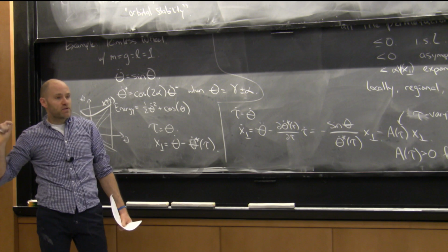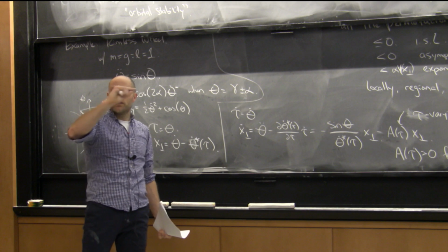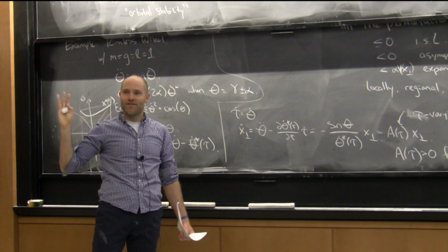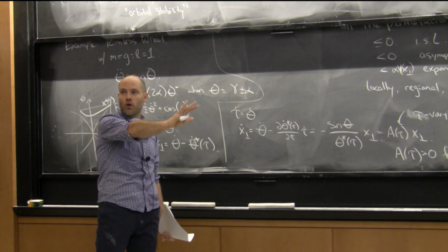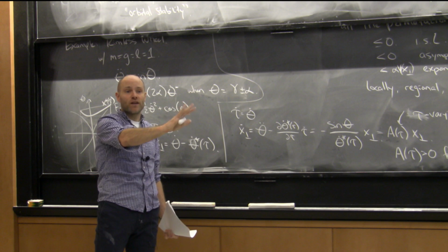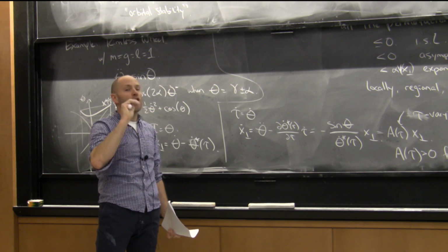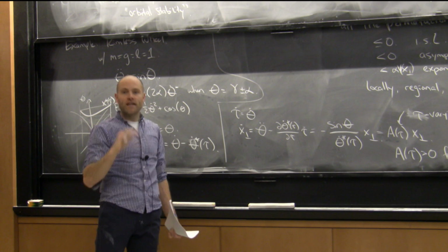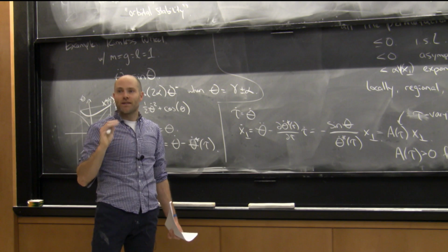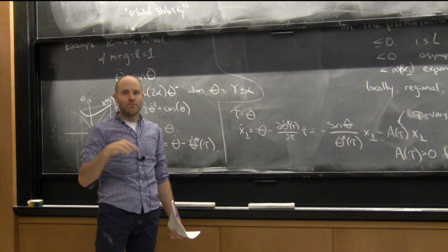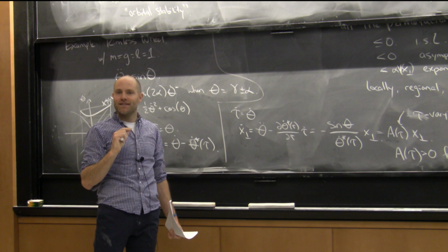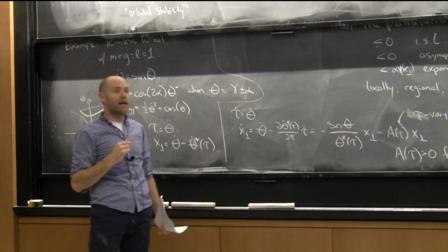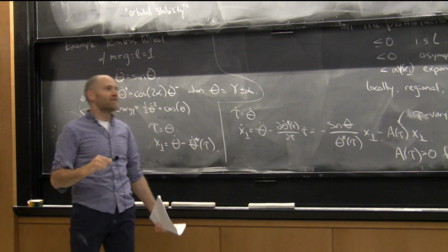You can have systems that in the short term diverge, but over time, ultimately, the integral of the total solution gives you something that performs well over time, but instantaneously, you're actually losing control authority. And that happens all the time in legged robots. So certainly, for instance, in running robots, once I leave the ground, I don't typically have any stability, right? My dynamics are governed by orbital mechanics, I guess, if you will, right? So just free-floating dynamics, right? I can't change my angular momentum, right?